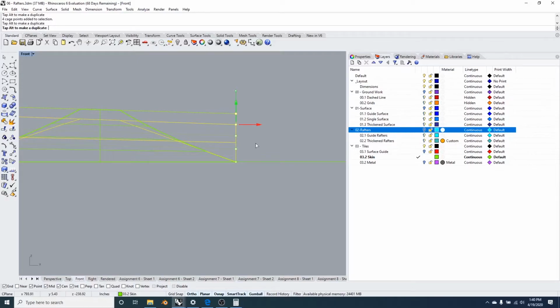That's a good thing that I should mention. If you have a point here, let's say this point, the one that I just selected, it's in the middle between these 2 points. Don't push it away in a way that it goes beyond this range of the 2 points, because you're going to start getting the surfaces to intersect with one another. So just keep the bounds closer to one another, but don't go beyond the range.